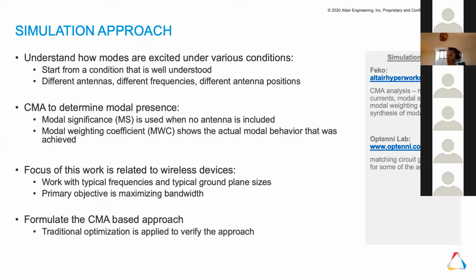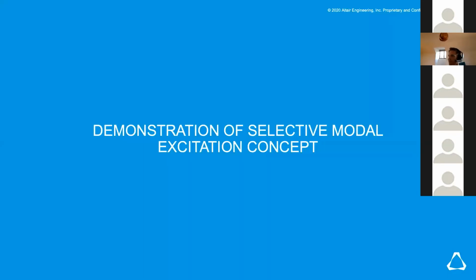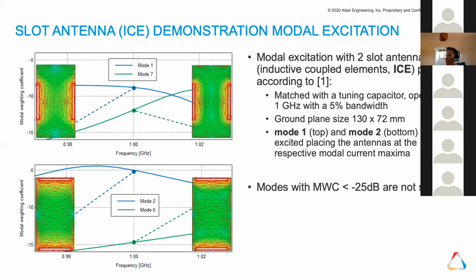The simulations were run with FEKO, and some of the designs that I will show were matched using OptiFEKO. As a starting point, we implemented a standard modal excitation configuration. Here you can see an inductively coupled element used to excite mode 1 in the upper graph and mode 2 in the lower graph, by placing the elements in both cases at the modal maximum in the modal current distribution.